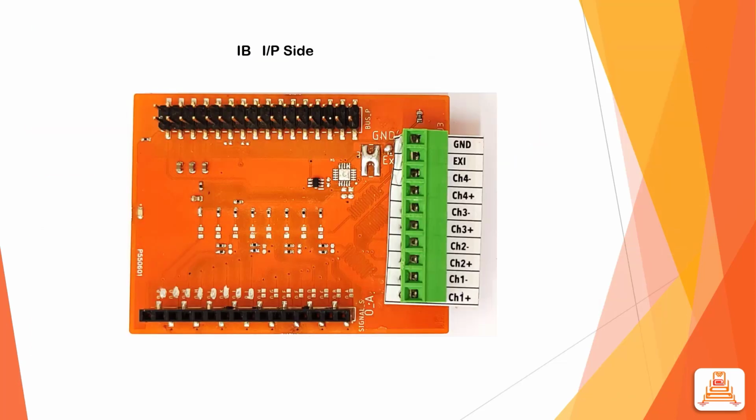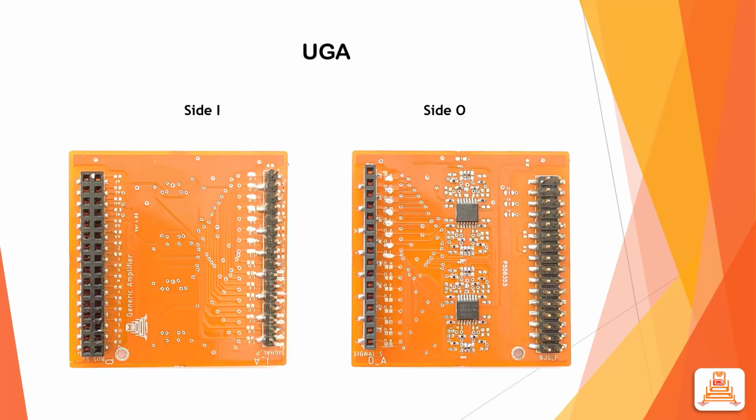In summary, the 8 FC28 sensors are connected to the input board and the outputs are routed to jumpers O1 through O8. These outputs are voltages of moisture sensor. They are given as input to the unity gain amplifier board by shorting the jumpers I1 through I8.